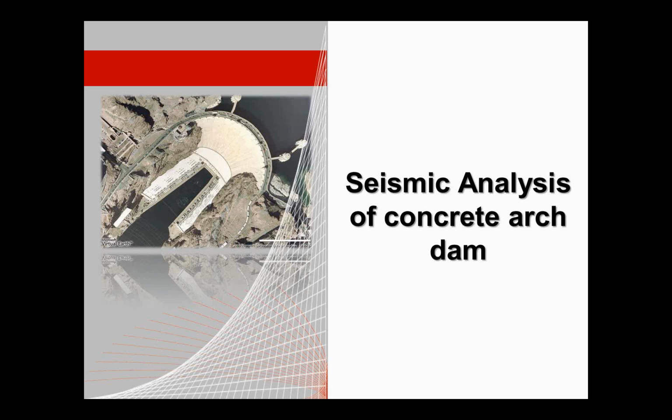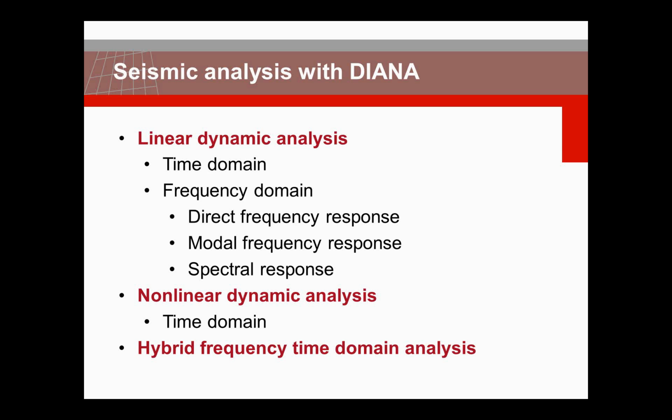That brings us to the last case study, which is a seismic analysis of a concrete arch dam. So in DIANA we have different types of dynamic analysis that we can use to assess the behavior of a dam under dynamic or earthquake conditions. We need to distinguish between linear analysis and nonlinear analysis, because if we have linear analysis, we have the option to do the analysis either in the time domain or in the frequency domain.